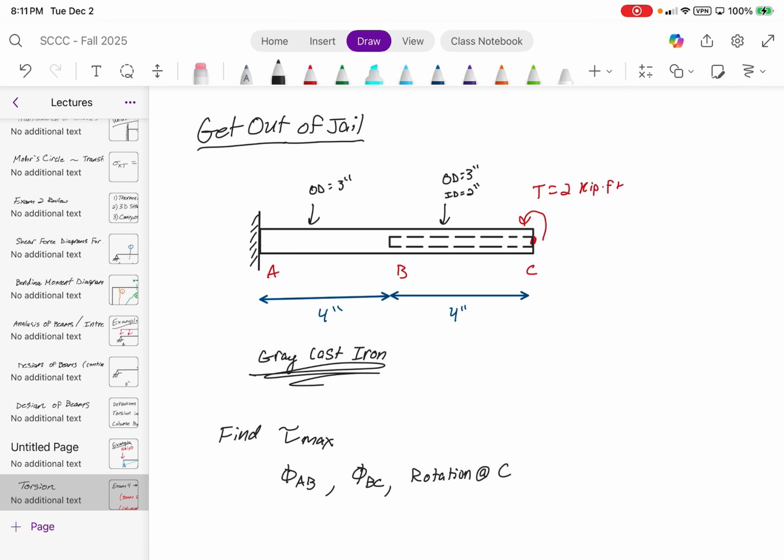There's a particular thing that we did at the beginning of the semester. If you have one bar that's elongating and then another bar that's elongating, what do you do? Cut sections and find compatibility? Not quite. It's like if you have one rubber band wrapped around another rubber band and you stretch it, what's the total elongation? It's going to be stretching both rubber bands, so what's the change in position going to be?